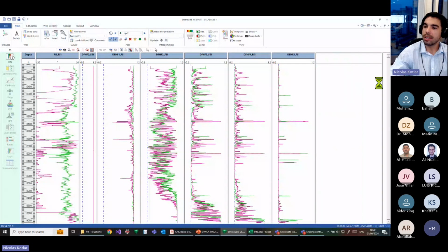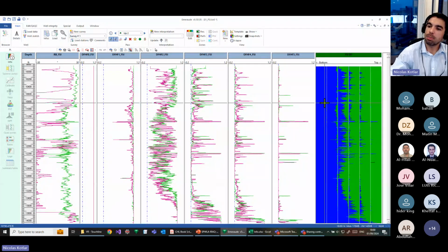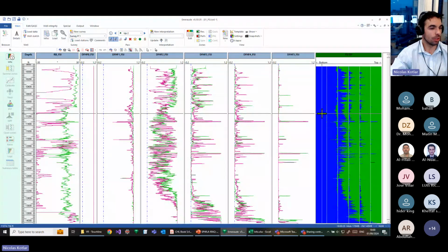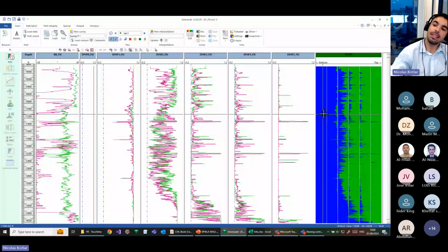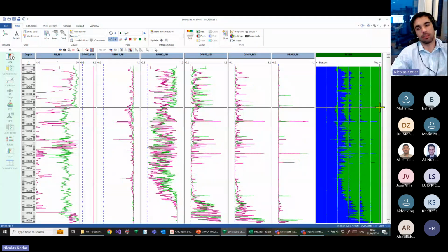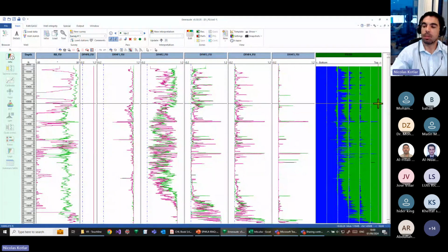So what are we showing here? Can you see that there are 6 bands here? 1, 2, 3, 4, 5, and 6. Each band shows the holdup distribution in the probe position 0, so in the tool body, until the probe at the top, probe number 5 in this case.